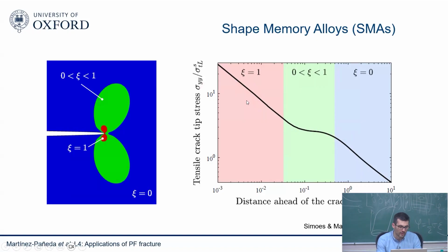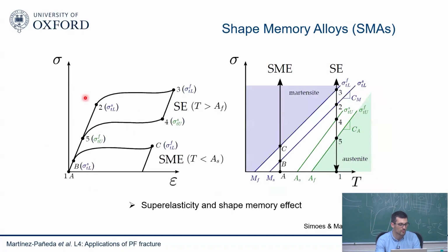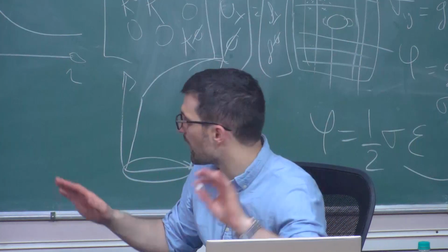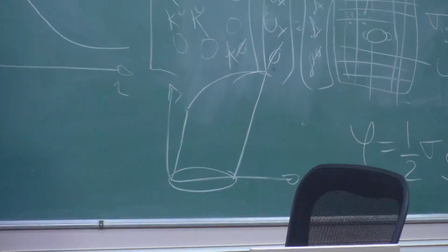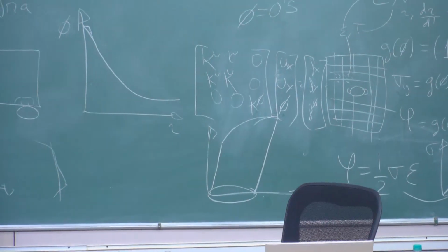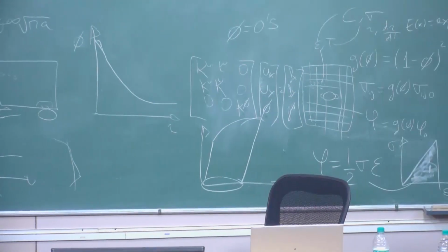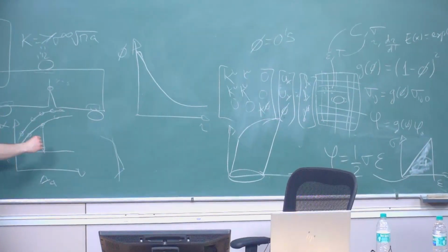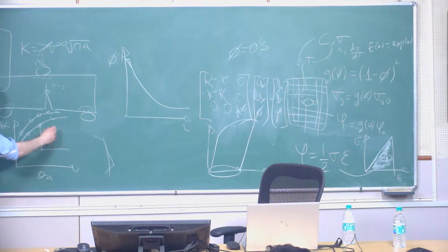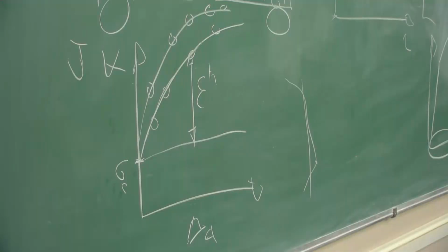So in terms of fracture, what happens is that these non-linear strains related to the transformation add a little bit of plasticity, so they bring some toughening effect. When we do fracture experiments on nitinol and other shape memory alloys, we see a toughening effect: the R curve, even though we haven't reached much plasticity, is not flat like it would be for a linear elastic material. We actually see a bit of plastic dissipation, less than with plasticity, but a little bit due to those inelastic transformation strains. We call them transformation strains. So there's some transformation work that creates toughening effects.